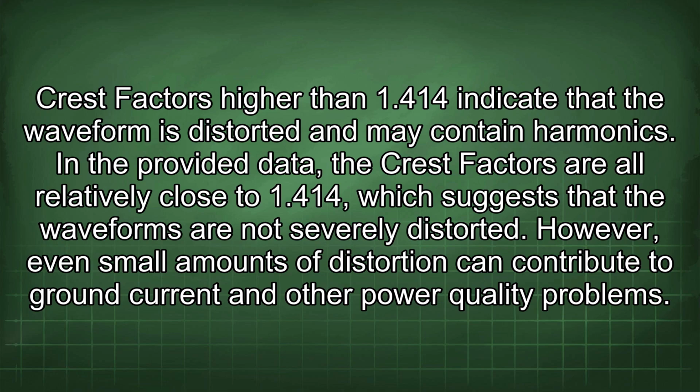In the provided data, the crest factors are all relatively close to 1.414, which suggests that the waveforms are not severely distorted. However, even small amounts of distortion can contribute to ground current and other power quality problems.